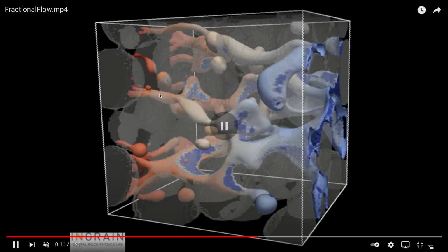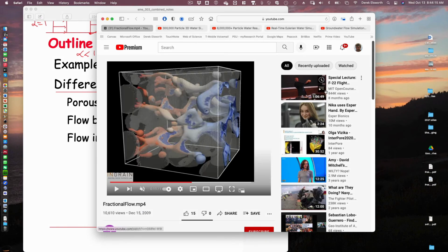Each one of these little tubes is just going through here. It's kind of an effective tube, right? It's changing in diameter as you go downstream. But each one of these tubes is exerting some drag on it due to friction. And this drag between upstream and downstream means that if you look at the pressure on this side of the cube and the pressure on this side of the cube, they'd be different. And they'd be different by an amount which is pretty straightforward.